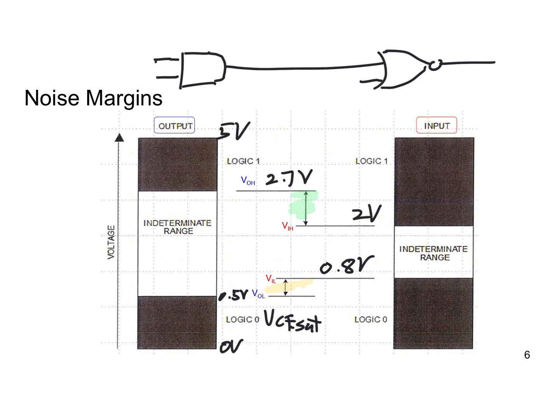You have to make sure that your logic levels on the output side and on the input side don't fall in that indeterminate range, because if they do, there's no guarantee that the system's going to work together. So the logic levels, whether it's an input or output, absolutely must, under all circumstances, stay within those specified ranges, and you never go in that indeterminate range, because then there's no guarantee how the gate is going to react. You're on your own at that point.